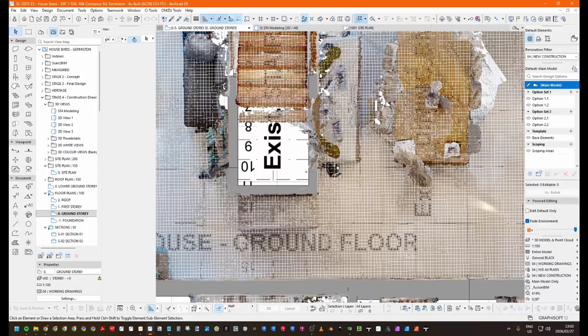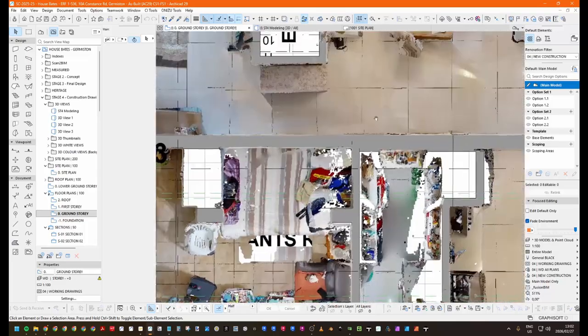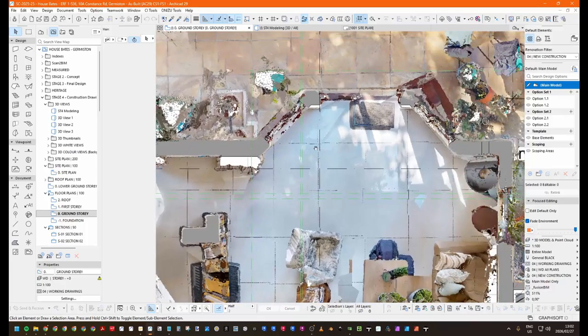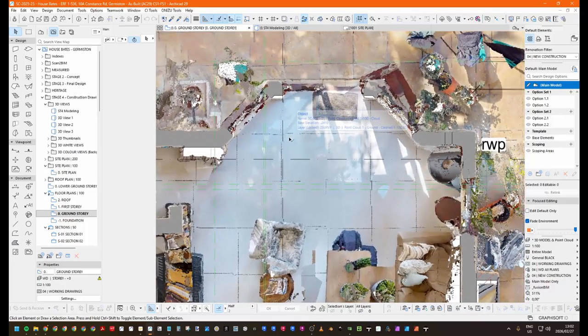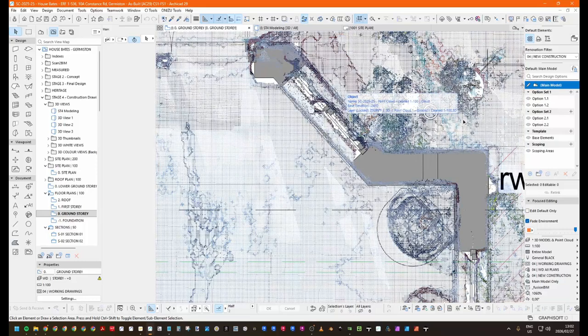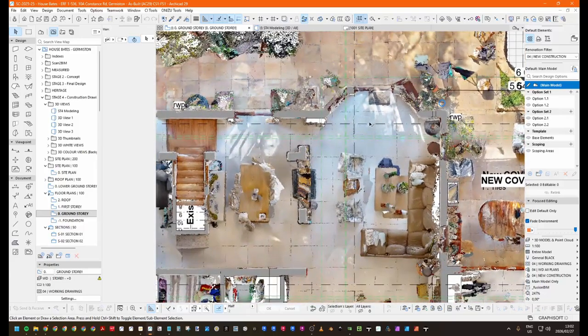And this is how we then utilize the point cloud along with the design model during construction to verify that the construction work is aligned with the initial design. The point cloud scan will then represent the construction work after the design, and obviously we're superimposing it on the initial design if it's a construction progress scan that we have done.